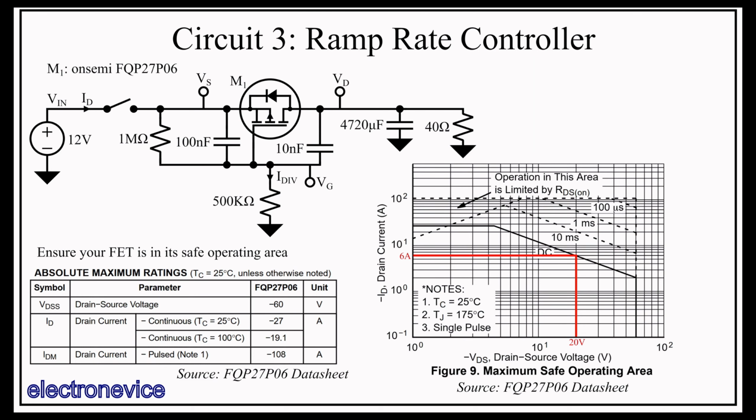To show what I mean by this, let's think about this circuit right from the point at which the V-in is applied. We'll assume a very small time frame. The source equals 0 volts at the start, and the switch gets closed extremely quickly so that the source is set to 12 volts in less than a microsecond. We'll also assume there is no significant inductance in the system. So, with such a sharp turn-on, the impedances of the capacitances are very low, and the relative impedances of the resistances are extremely high. Additionally, the drain-to-ground capacitance at the load is assumed to be so many times larger than the gate drain or drain source capacitance that we can essentially treat the drain-to-ground capacitance as a short. So the drain is shorted to ground, and the circuit really looks more like this.